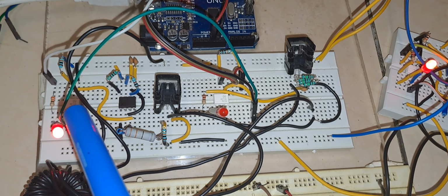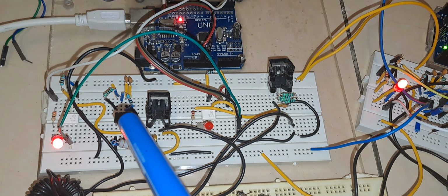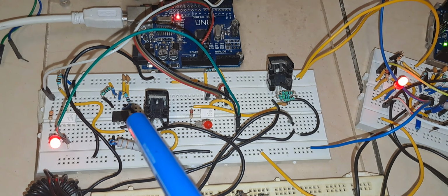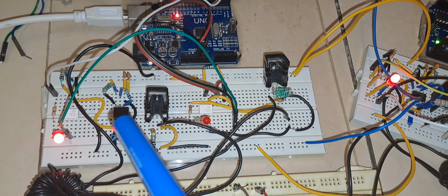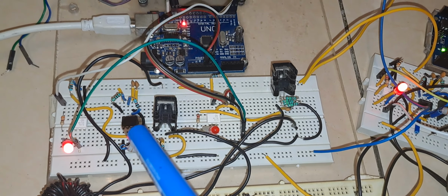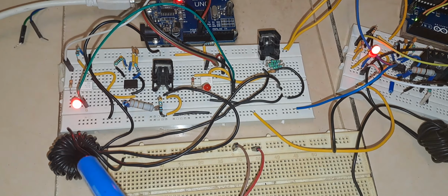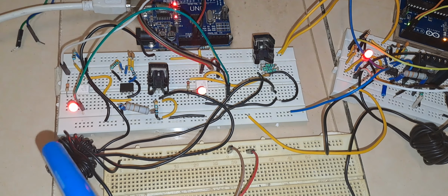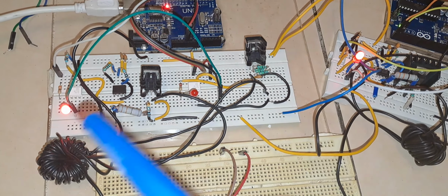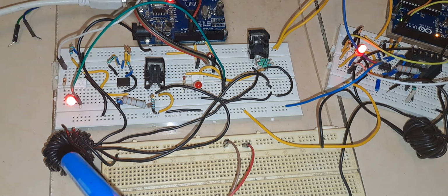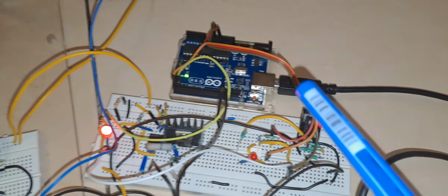It is optically isolated and it is fed to the modulation stage, where it is modulated with a carrier frequency of 48 kHz. Please watch the ASK modulation technique videos, the previous videos. It will be very clear how the modulation is taking place. After the modulation, the data is fed to this power MOSFET, and the power MOSFET is driving this transformer. This transformer has three windings. One winding is the transmitter winding, one is the receiver winding, and one is the coupling winding for the transmission line. So this is the transceiver 1 and this is the transceiver 2.